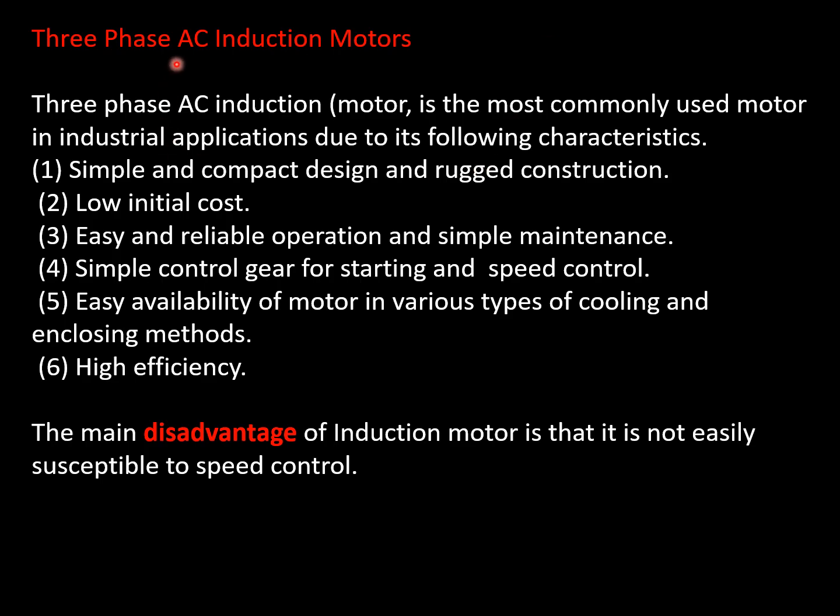Friends, now we'll discuss the characteristic features of three-phase AC induction motors. Three-phase AC induction motor is the most commonly used motor for industrial applications due to its following characteristics. First, simple and compact design and rugged construction. Second, low initial cost. Third, easy and reliable operation and simple maintenance.